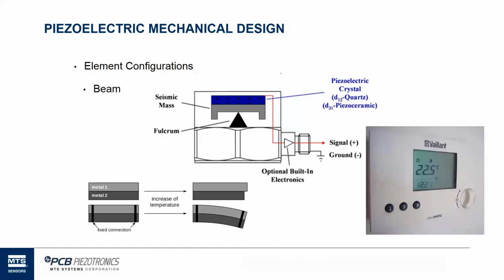And that's one thing we found when we used these a long time ago, is that if we got into high thermal transient type events, say we'd open the doors to an aircraft hangar or to a test bay in a dynamometer type environment, that inrush of air would change the temperature on the surface of the accelerometer, and we'd get output due to that temperature while we're taking vibration data, and it could wreck our test data. So we've matured more.